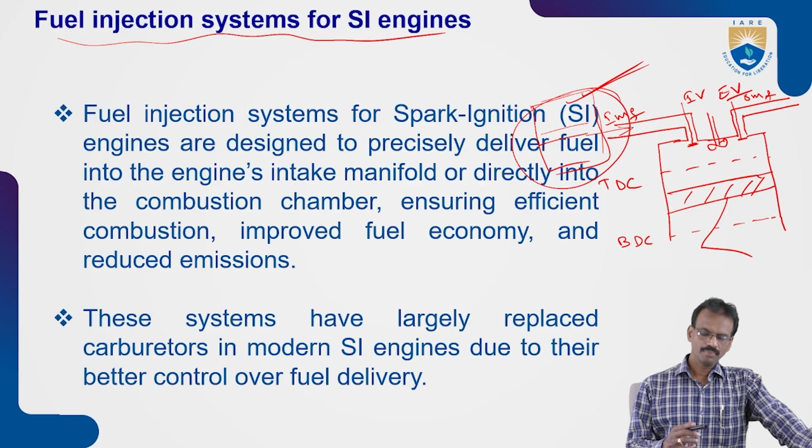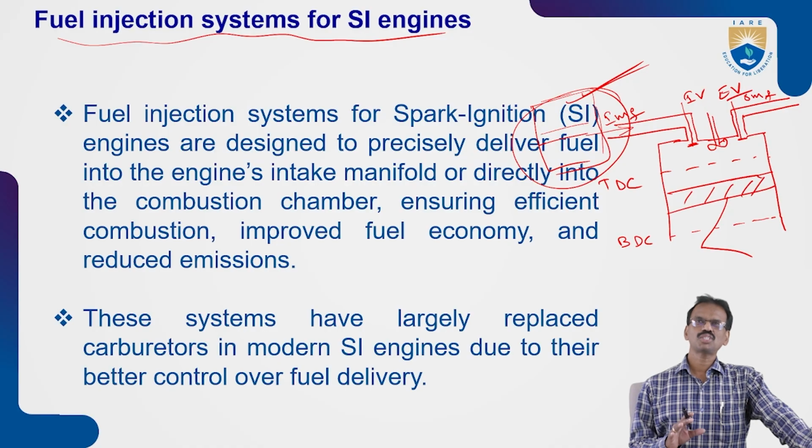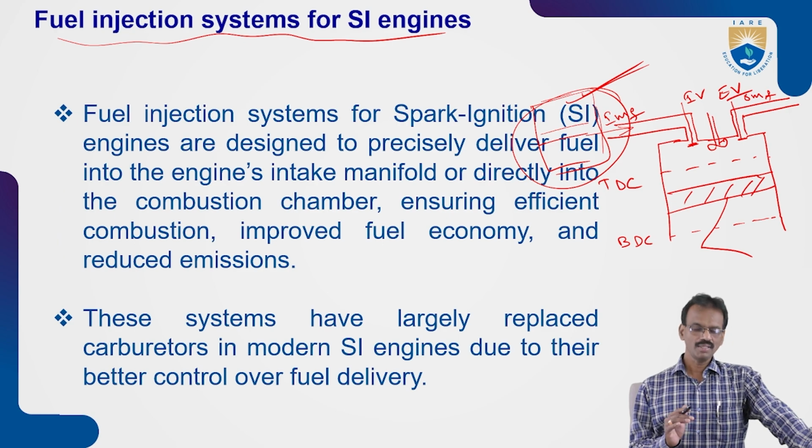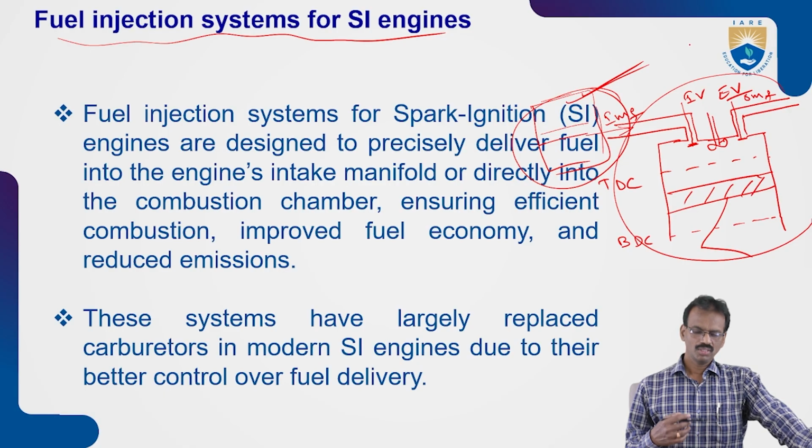There are a few more drawbacks for the carburetor. Based upon the climatic conditions, carburetors don't work functionally, because it leads to engine starting problems. In starting, the carburetor should provide an over air-fuel mixture, but it fails to provide according to the need, the volume of the charge.